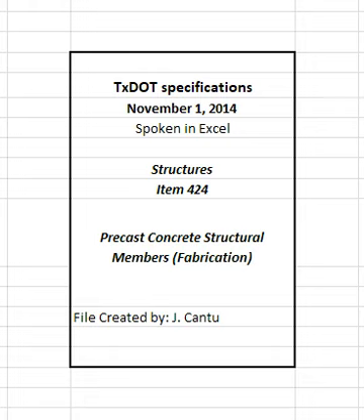Remove excess form release agent from the form surface before casting, and ensure it does not contaminate strands, reinforcing steel, and embedments. Use a clear form release agent of the same brand throughout the casting of retaining wall panels per structure, unless it can be shown that a different form release agent does not change the appearance of the concrete. Construct the forms to facilitate removal of members without damage to the concrete.